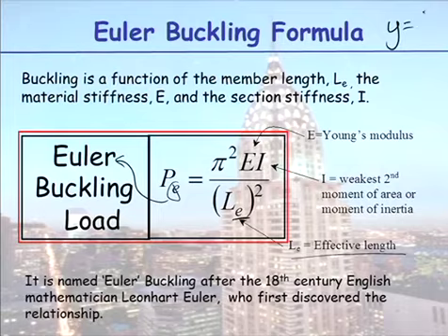What's she talking about? If I write y is equal to 1 on x squared and I ask you all what that looks like, what are you all going to do for me? That. Yeah. So when x gets bigger, you know y gets smaller. When your length here gets bigger, your buckle load gets smaller. I can buckle this easily. When I start shortening the length, I have to apply more and more load to the system.